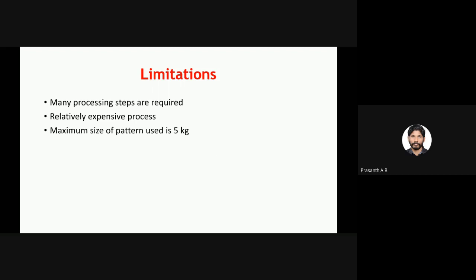Then the other thing is the maximum size. There is an upper limit for the pattern because you know that wax is a soft material. So if the weight is increased beyond 5 kg, because of its self-weight it may undergo deformation. So up to 5 kg we use. For investment castings, we use patterns only up to 5 kg.